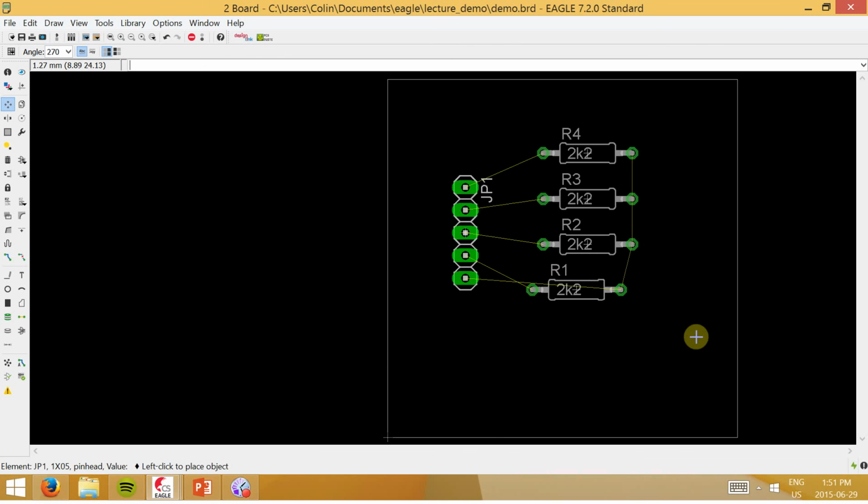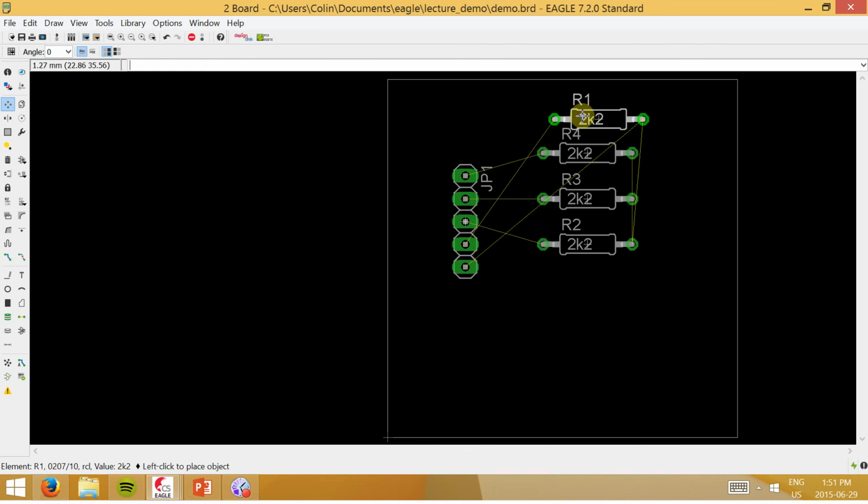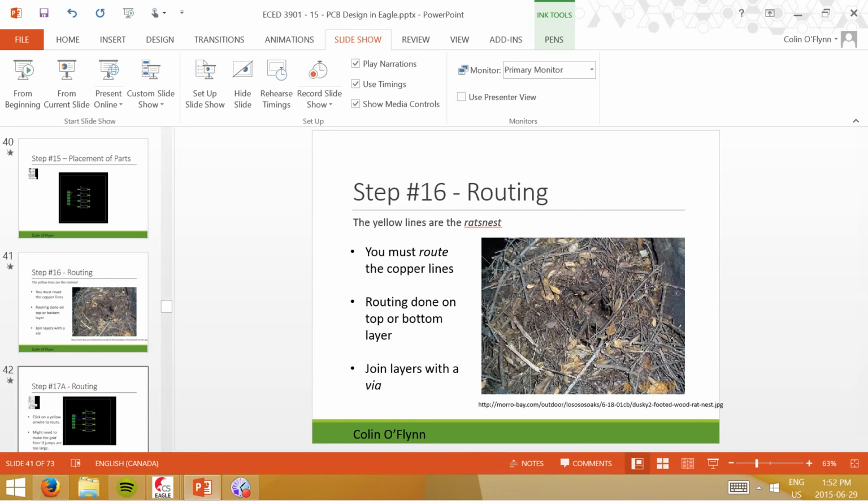So I might continue to rotate it and say, okay, that looks nicer because the lines aren't crisscrossing anymore. Similarly, when I'm placing parts, this is a valid placement, but it's nicer if it's down here, because I know it will be easier for me to route this board once I do the routing in like 30 seconds here.